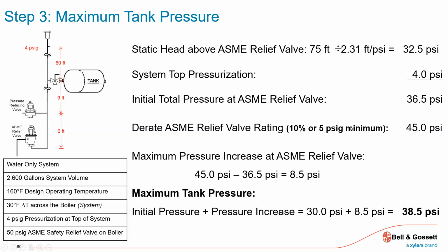One thing to be aware of is relief valves. In this case, say we have a 50-pound relief valve. It's known in the industry that the diaphragm spring tension on that relief valve will start to weep just a little bit before it gets to, in this case, that 50. So as a safety factor, they'll say derate the valve when you're doing your selection to 10% below 50.